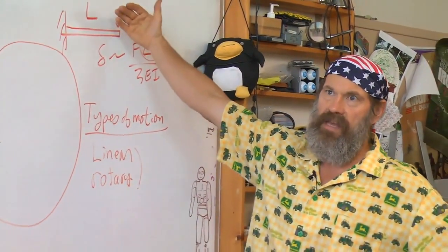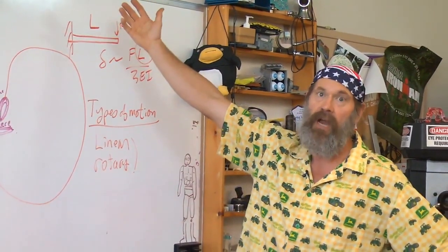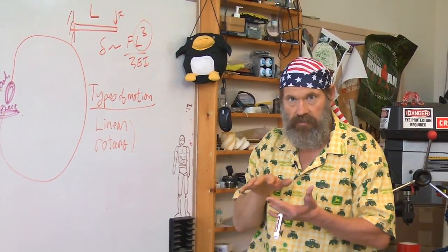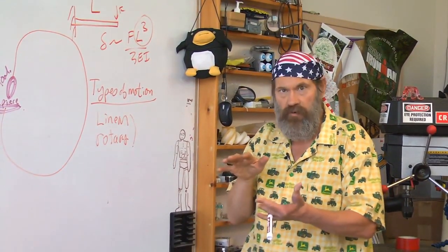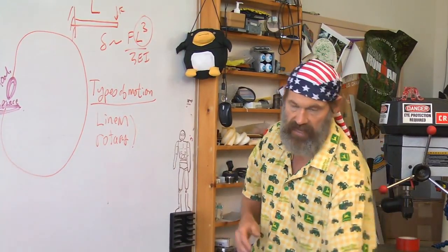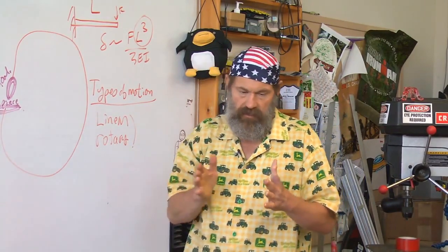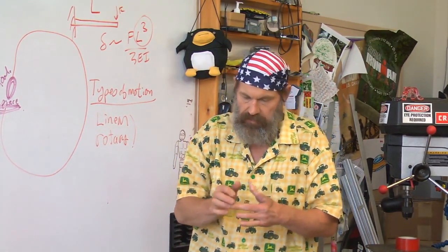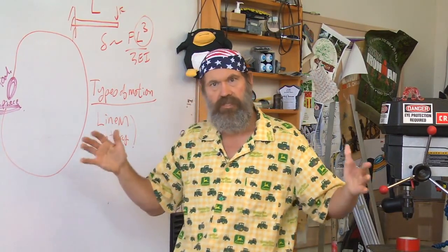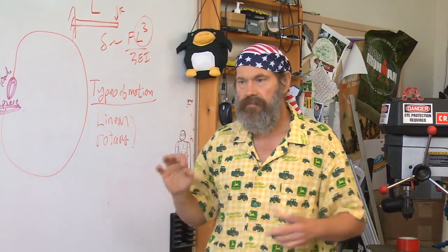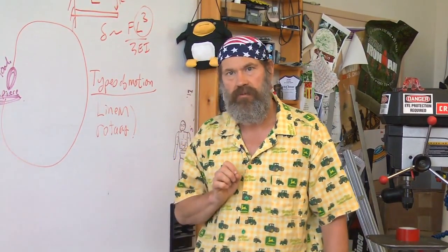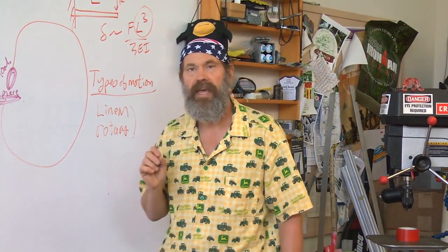So having a great big machine to accommodate any size part when you're mostly operating on little itty bitty parts may start to tell you that the cost of that machine is going to go way up in order to give you the stiffness you want for operating in the small zone, and you may be far better off having a family of machines that will handle from small to medium parts, and then from medium to large parts, and then large parts, as opposed to one machine that you're going to use for everything. Okay, so that's another key point. This is not only true when you're designing machines, but when you're buying machines to accomplish a function, what you may expect to pay.